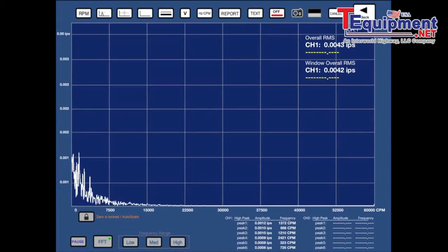So jumping into the spectrum, I'm going to turn on a 1G shaker here, which we're in inches per second now, but we'll convert over to acceleration in a moment. You'll see how that measures the 1G shaker. But normally we were able to only save one spectrum per report. And that would unfortunately make us have to do one report for velocity and one report for acceleration.